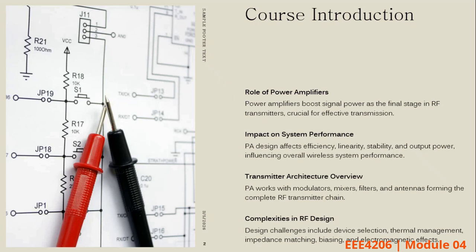And then on the other side, you have the output matching. At this time, you know what matching means. This matching stage is to ensure that the signal is not reflected back to the source to cause heating and also standing wave ratios. And then finally, you deliver your power into the antenna. That will be the final stage. We shall look at this block diagram, and you will also design one. And in the coming weeks, we shall also do practicals on how some of these are designed and simulated as well.